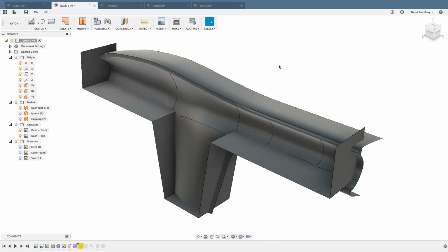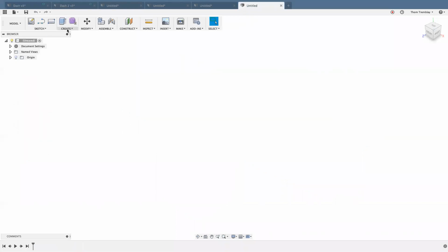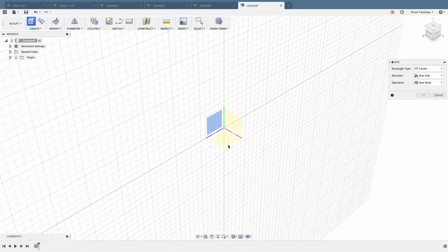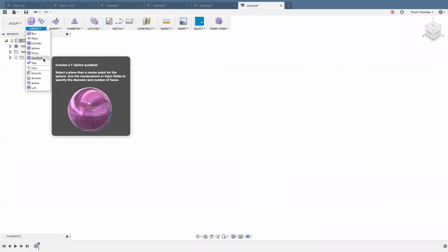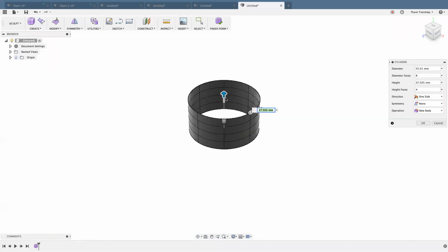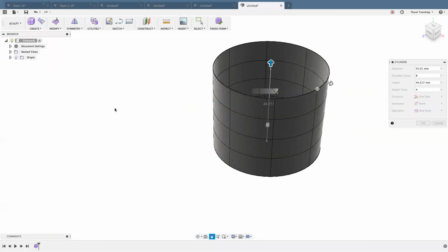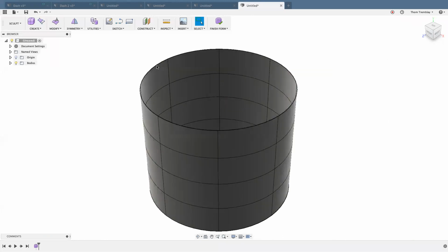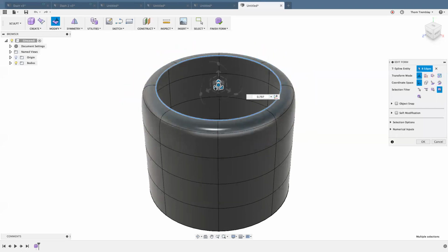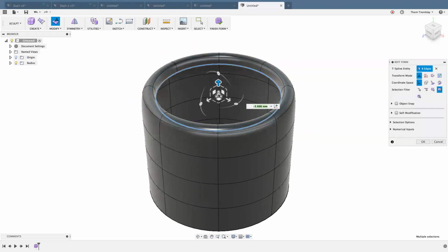The other thing capping can do is this. So let me just move this dashboard over to this display, excuse me. So let me create a new model. This is an exercise that Professor Smith saw at Art Academy a while ago. So let me start out with a cylinder, and I'll just do it partial. Okay, so let's say I want to create a control knob for a radio. I'm just going to use edit form with the Alt or Option key to scale this in, to create some additional faces.